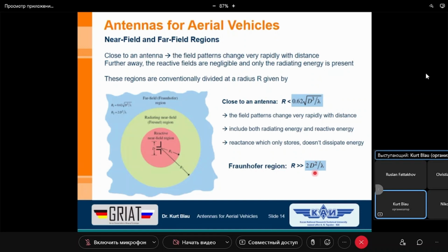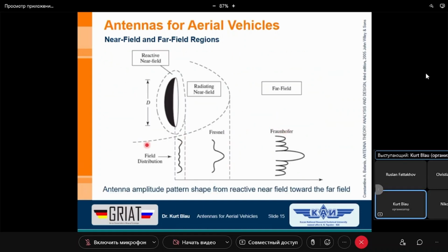We can square it because we have only calculated the quotient here. Then we have to multiply it again by the dimension of D, 900 millimeters, multiplied by 30, multiplied by 2. Then you can see it's, let's say, 0.9 meter multiplied by 2, it's 1.8 meter, multiplied by 0.3. Then you must realize a distance of several meters. This distance, which ensures the Fraunhofer region, is also valid, for instance, for your receiving antenna.